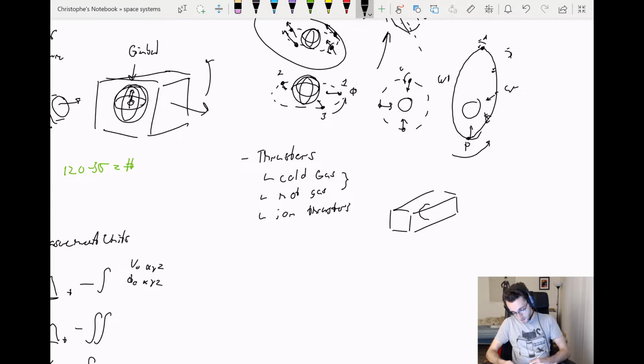is you typically have a tank or reservoir of compressed gas, and then you have nozzles spaced out along your space vehicle. They're connected by pipes, and you have different valves along these nozzles. What you do is you basically open and close these valves for given amounts of time, allowing the gas to escape. And where there's an action, there's an equal and opposite reaction. So as the gas leaves your nozzles, your space vehicle will be imparted a force in the opposite direction.